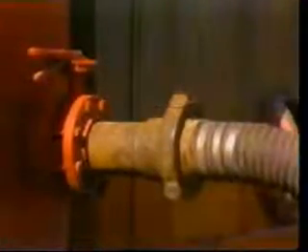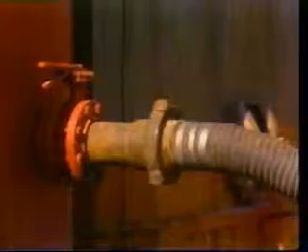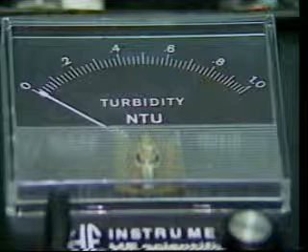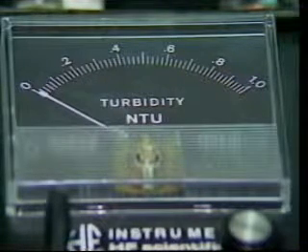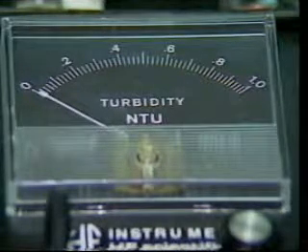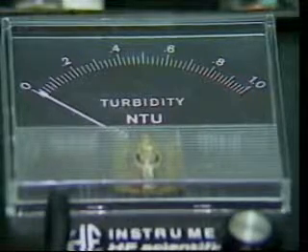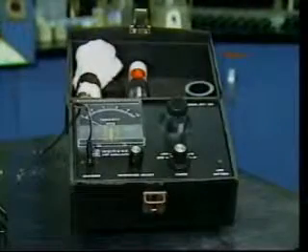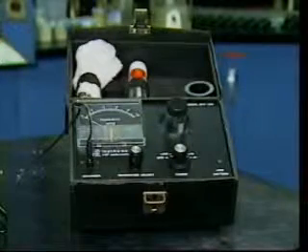The tanks used to hold the treating fluid must be clean and contain no damaging chemicals. Analysis of the treating fluid using a turbidimeter should indicate not more than 20 to 100 parts per million total suspended solids, depending on the formation. The treating fluid must be compatible with the formation so that no damage will be caused by swelling clay material, scale precipitation, or emulsions. The addition of a gelling agent to the treating fluid is required to achieve the viscosity necessary for transporting the gravel pack material.